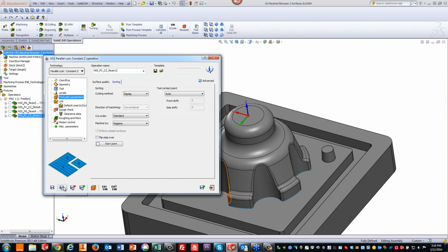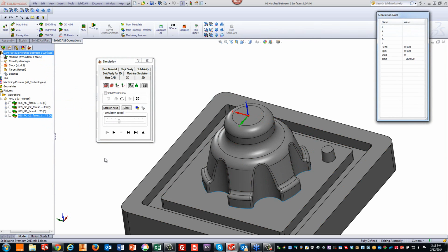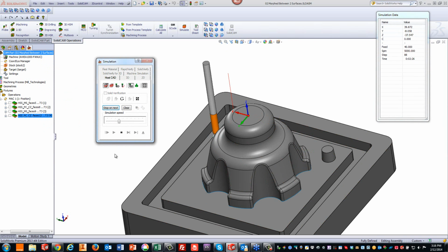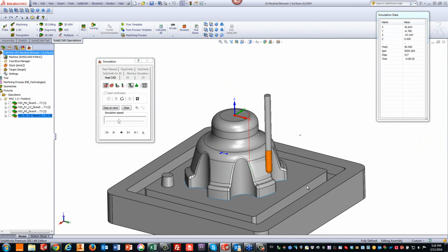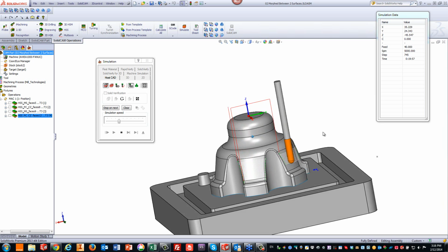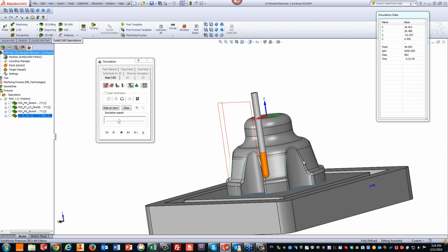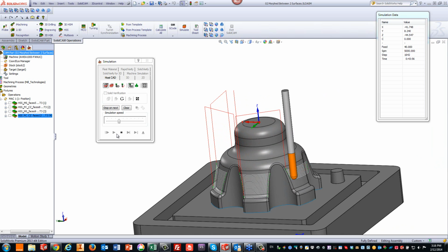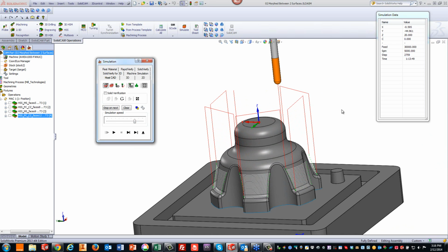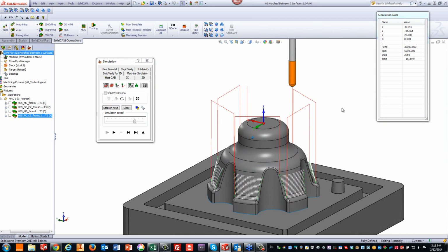Let's take a look at the toolpaths we have now. You'll see that it's working on that particular surface. And when it finishes, then it goes to the next surfaces, and it's not jumping up all the time anymore. It's just going once to its clearance level, and then it finishes that area, goes to the next area, finishing off each area exactly the way I wanted. Now, we finish this off all the way to the end, but you know what?